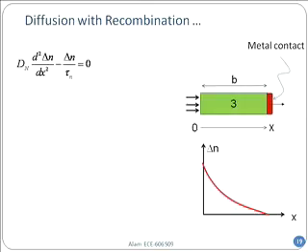Do you know the solution of this equation? That's how it looks. Almost like a Schrodinger equation, right? Does it look almost like a solution of the Schrodinger equation? No surprise. Because look, the first term with the second derivative and the potential term on the next one, they are exactly the same equation. Of course, they should have exactly the same solution. So I have that. L sub n is called a recombination length. This is the square root of D n tau n. So that's what it is.